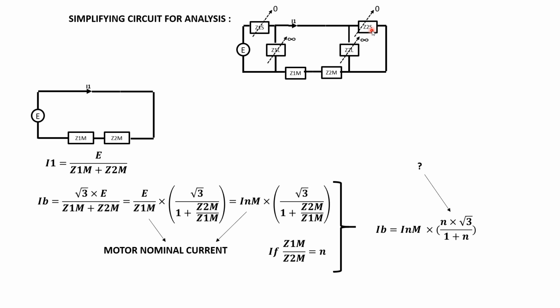So that is a sort of controlling voltage, sort of zero value, kind of infinite, but kind of. Otherwise, if you are going to study voltage drop things, that's a different thing. But for us, we can say that they are zero. So it's very, very simplified. In this case, we adjust a source voltage in per unit in phase, and we have the positive sequence in series with the zero sequence impedance of the motor. So I1 is equal to the per unit voltage of the system in phase divided by zero sequence plus positive sequence.